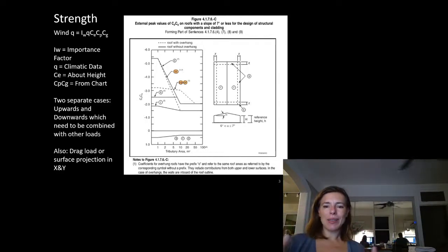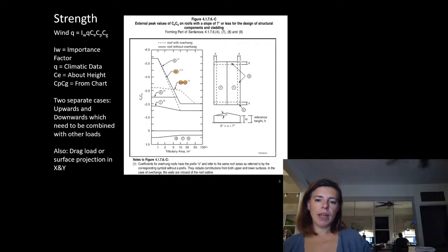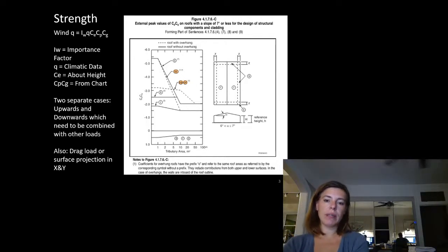This kind of implies that there's walls around it, that's a small section. It's a good place to look up these values. It can be a bit conservative. I don't mind this for small scale elements where snow is usually the governing load anyway, because we find that it doesn't have that big of an impact on the overall design.